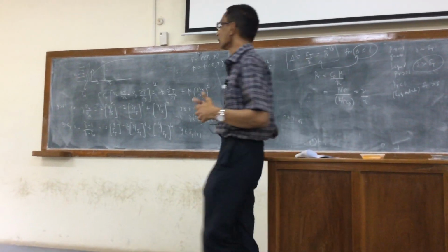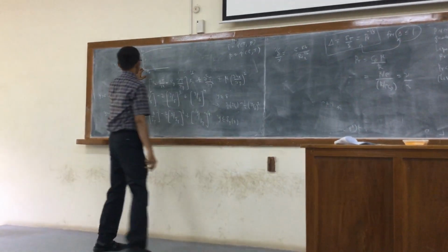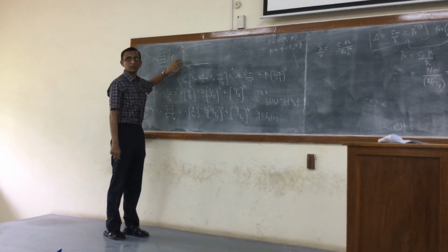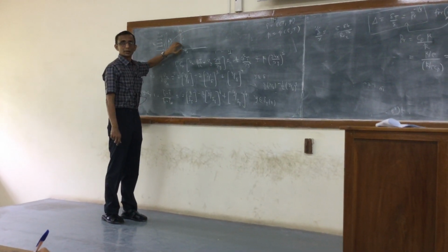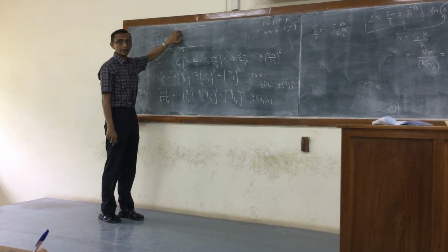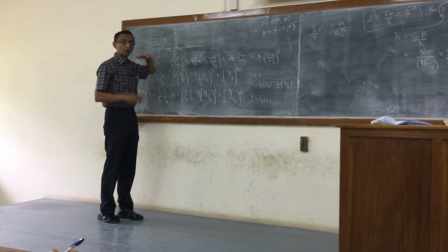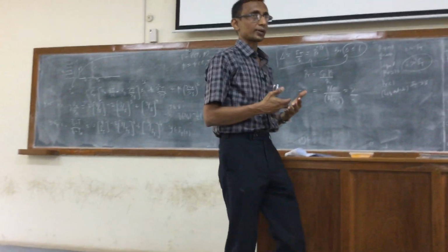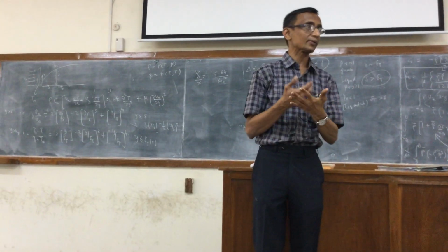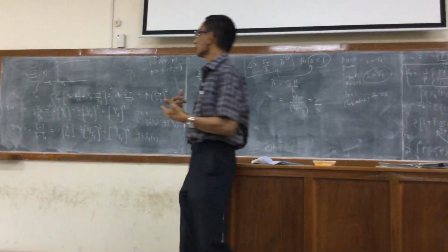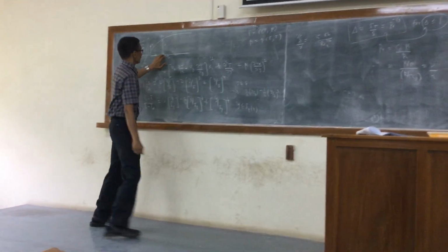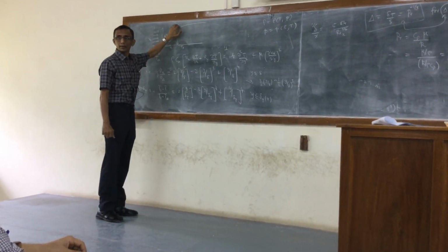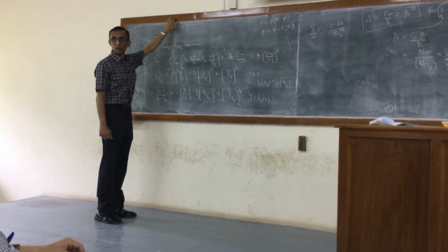So we have seen that this can be physically interpreted as a measure of the diffusion of the vorticity, because we always associate vorticity with the no-slip boundary condition. Vorticity is being generated because of the presence of the wall, and if the velocity is actually zero here, it's taking a longer distance to reach V naught.